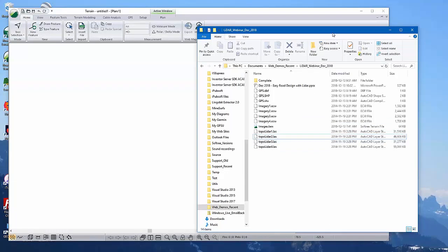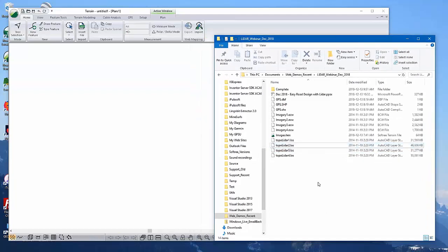As far as formats for LiDAR, we recommend LAS format. I know that there's some advantages to grid formats and DEM formats because they save on disk smaller, but in terms of using them in RoadEng, we have to expand them into a 3-dimensional file, and the advantage of using the grid format quickly disappears and you get a ton of points. In fact, it oversamples the data, and it's not the best way to go. So if you have a choice, if your provider gives you some options, ask for LAS format. It's quite convenient.